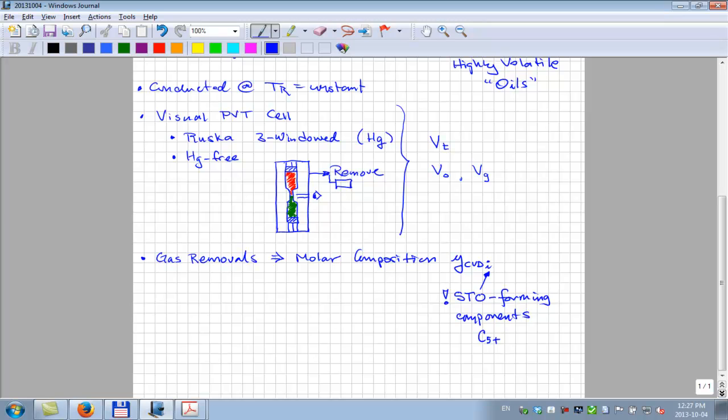And if you have any cooling that goes on between the exit point where you're taking something out and where you actually collect the sample, if the high pressure metal lines that you're removing it in are at a lower temperature than what's in the cell, then you'll get condensation. And what condenses first? These components that you're mostly interested in.